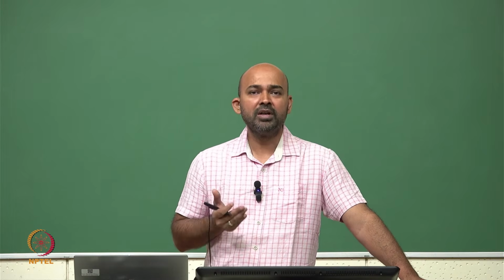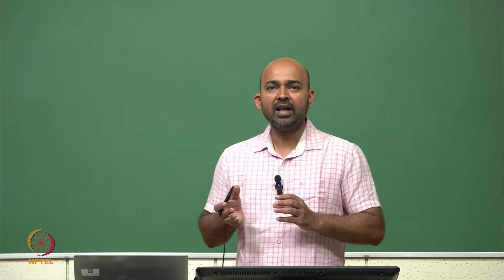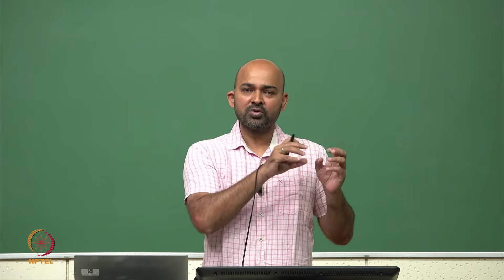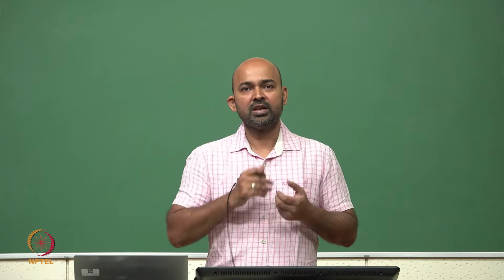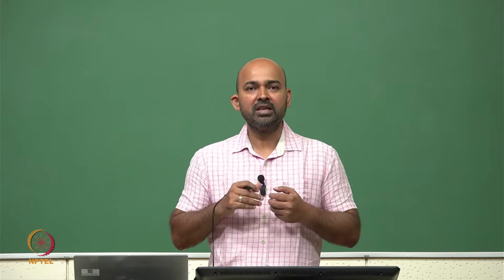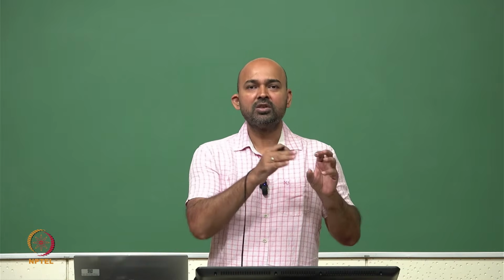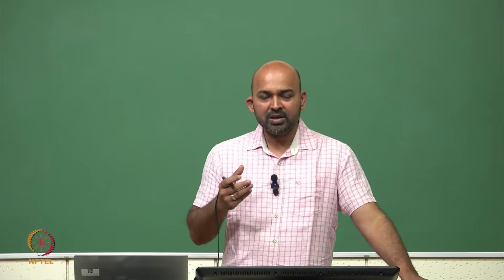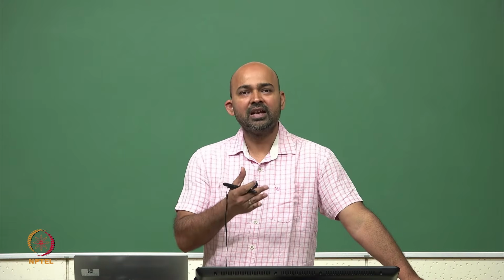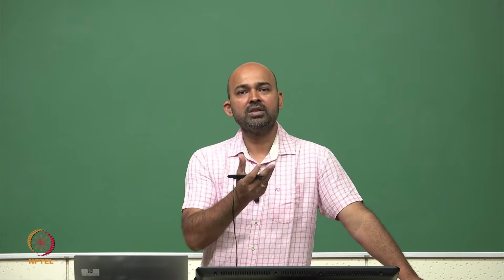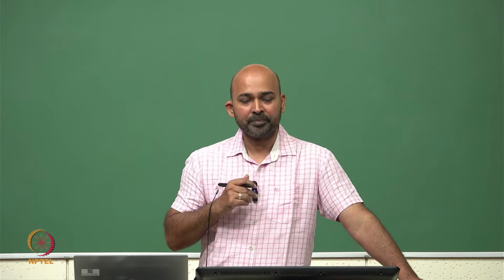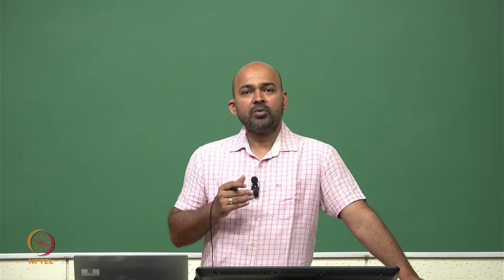Now, last lecture we discussed something called operating point analysis. Operating point analysis is when we are given a circuit and we assume all the components are linear, time invariant, and our sources, which are voltage sources or current sources, are not dynamic in nature; they are fixed values and are not changing with time. So, operating point analysis is the steady state analysis: what will be the output of the circuit at time equal to 0.